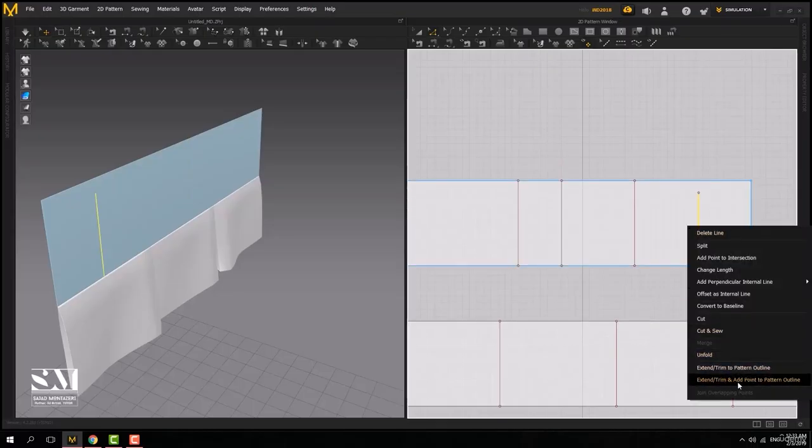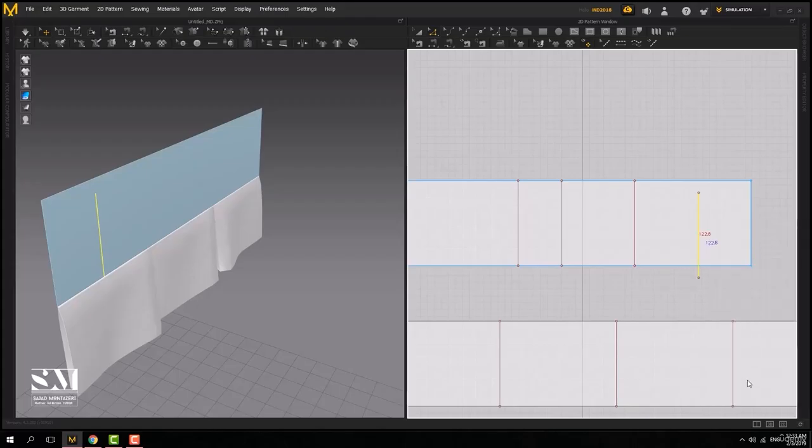But if I move the second one with add point, you'll notice that when trimming or extending, it also created a vertex at the intersection. So that's the difference, and we just compared them. This point is extremely important, so pay attention to that. Now I'll delete both, and clear this whole set as well. So I delete all of them. There we go.